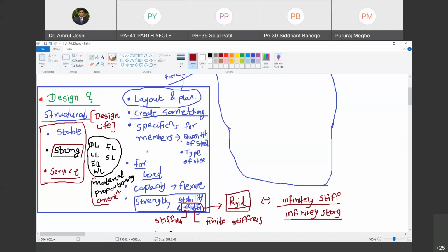For example, all of you are aware that when the World Trade Center did fall, it was not designed for the excellent plane crash loading. अगर डिजाइन किया रहता तो वो स्टेबल रहता वहां. Are you with me? Yes, sir, we are. Structure is only that strong जिसके लोड्स जो लोड्स के लिए आपने उसको डिजाइन किया है. If it is subjected to unprecedented or unimagined load, then it is going to suffer. So the foremost task in the designer's hand is first of all to envisage all the loads that the structure is likely going to have during the design life.